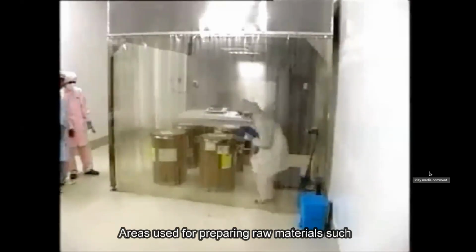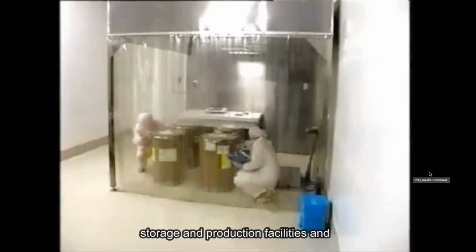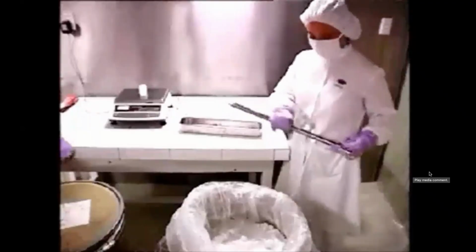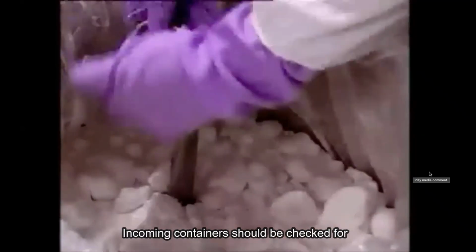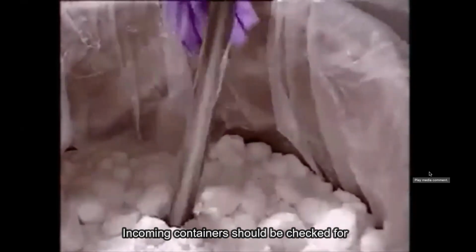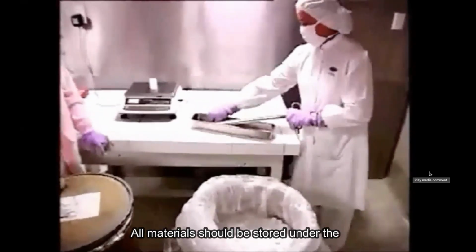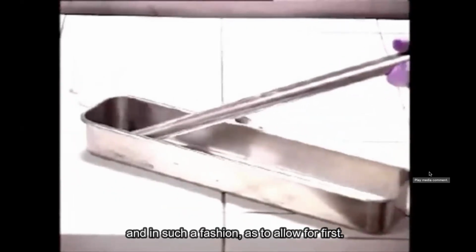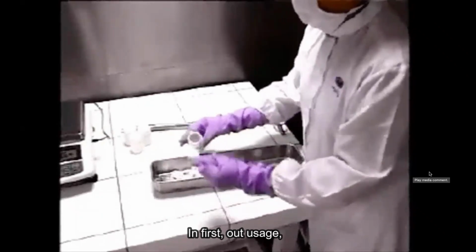Areas used for preparing raw materials, such as sampling, should be separate from other storage and production facilities and designed to minimize contamination. All materials should be regularly tested and closely monitored. Incoming containers should be checked for integrity of packaging and seal before sampling. All materials should be stored under the conditions stipulated by the manufacturer and in such a fashion as to allow for first in, first out usage.